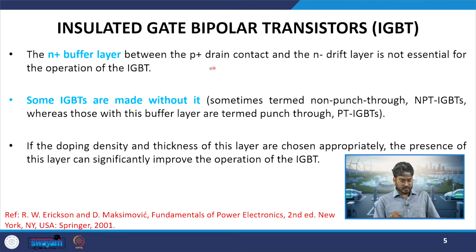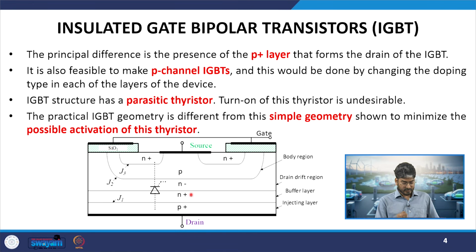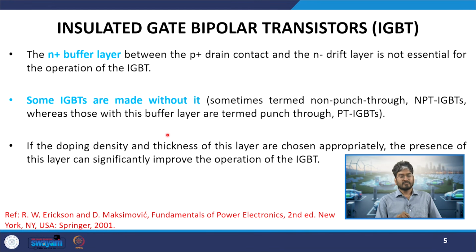Okay. So it is called an asymmetrical IGBT or punch through IGBT, where we will have this N plus buffer. As N plus is written, the concentration will be higher. So P plus is having high concentration and N plus is having high concentration. When we have high concentration of doping material, the blocking voltage or the blocking capacity of the junction decreases. Because of this, it will not be able to block your reverse voltage. So we say it is an asymmetrical IGBT, because its reverse blocking voltage will be less compared to your forward blocking voltage.